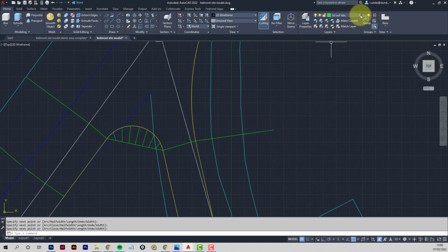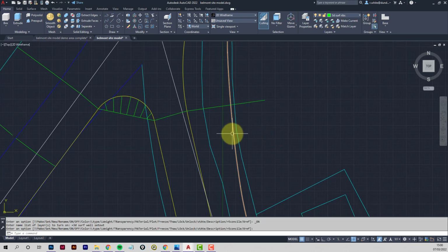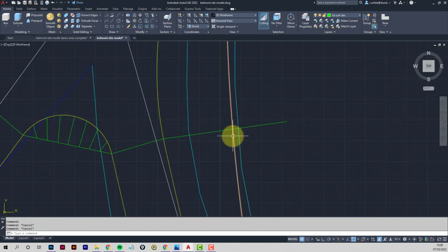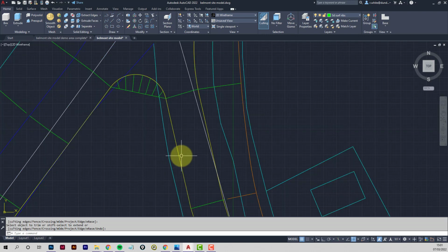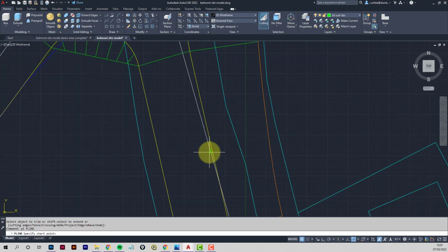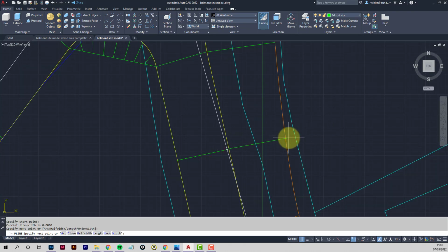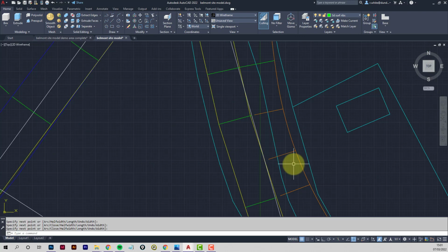Now I do have a line drawn for this, so I'm just going to show you. What I did in 2D is also create a nicer shape for the stone wall. So what we can use then, we can trim off the rib with the wall. I'll maybe introduce another one here. We've got a bit of a bend in the road here, so I'll go from spine to wall, and then from spine to road to wall. So we're picking up the changes of direction in the wall.